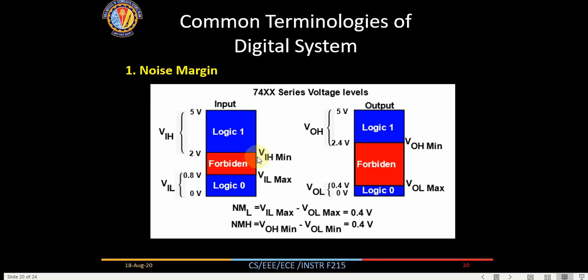No, it is like, for a TTL gate, when we read about the internal circuit, I can't be very sure that it will give 5 volt. Depending on how many gates it is driving, how many input signals you have, this output voltage can differ a little bit. That doesn't happen in CMOS logic, but in TTL logic and all BJT circuits. So the output can be anything between 2.4 to 5.